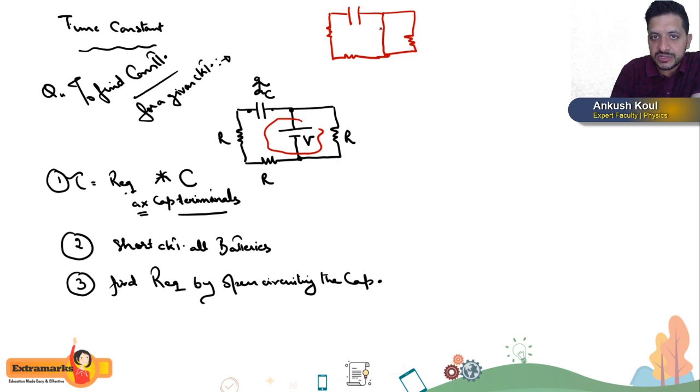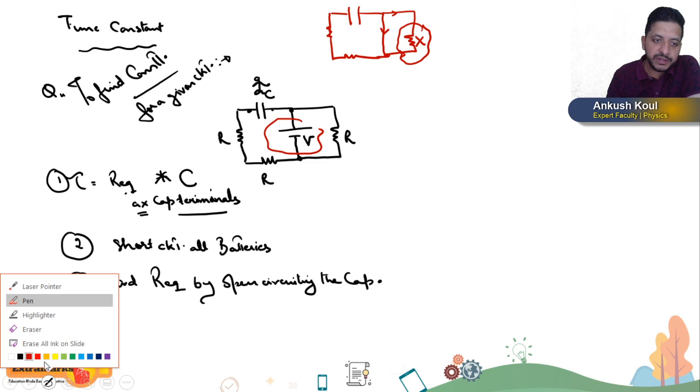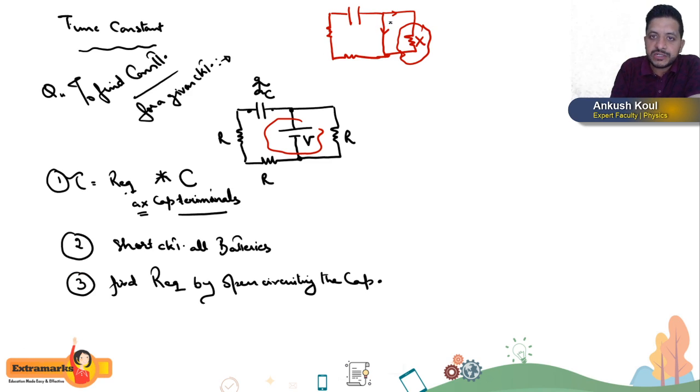If a battery gets short circuited, then whatever comes parallel to that short circuit loses its significance, because no current is going to flow through this part of the circuit when we apply some external battery sources. So whenever a short circuit comes in parallel across any circuit element, this circuit element loses its significance, and it is better we throw it out of the circuit.